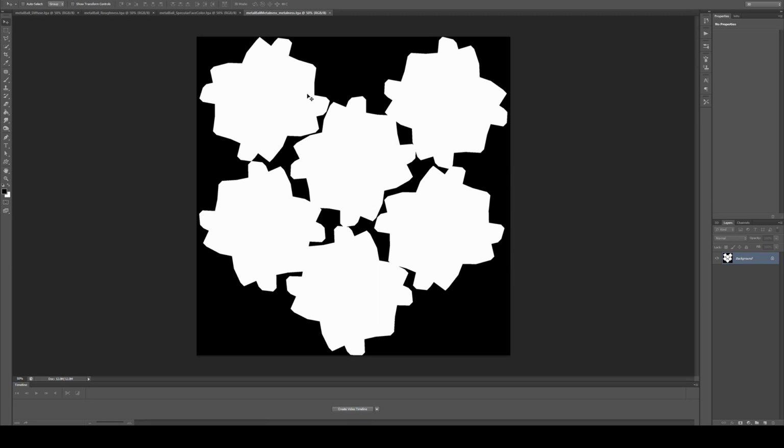You'll see the metalness just consists of a black and white layout. Now all this is a mask. So we could actually use this as a mask to mask off the areas for the object that are metal. Now this entire object is metal in this case, but you might have some areas of your mesh that are only partly metal or have some amount of metal to them. So you will have a similar looking mask, and I'll show you how to hook that up in a moment, but we'll just compare the rest of the maps first.